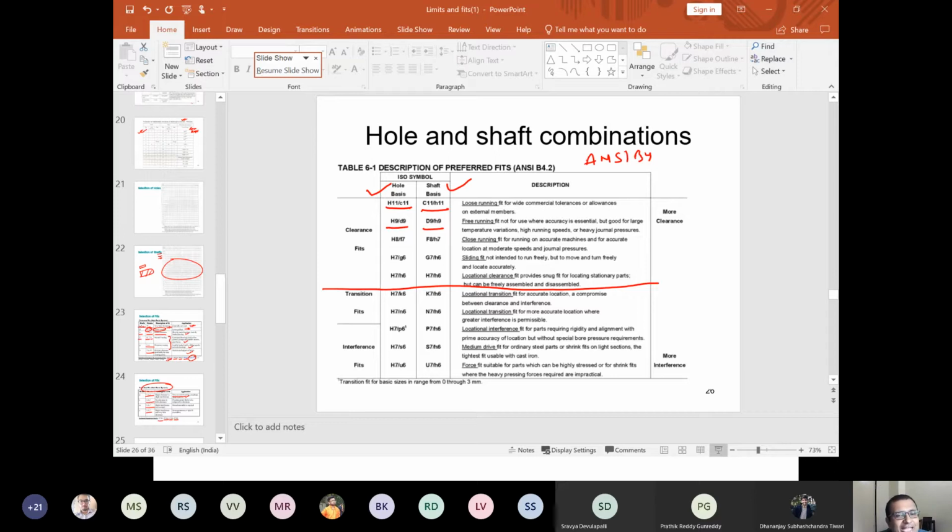So you'd think that they have done it dimensionally inconsistent. It's not dimensionally inconsistent. For an engineer, this makes more sense, because diameter is never measured in microns, and tolerances are not measured in millimeters. Tolerance will be 5 micron. So on the shop floor, nobody will say 0.005.